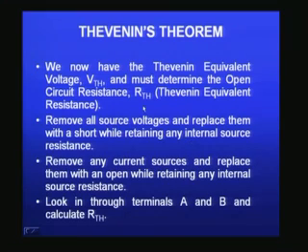Now, we have got the V Thevenin. We should now measure or calculate R Thevenin, which is the open circuit resistance across the load. Now, for this, what we have to do? I have already explained to you, we should just replace all source voltages by a short. You replace the voltage sources with a short, current sources with open, and include any internal resistance that may be present along with the voltage source.